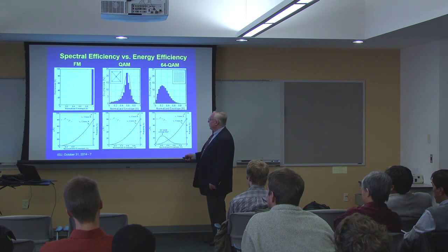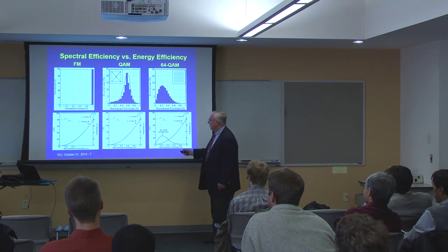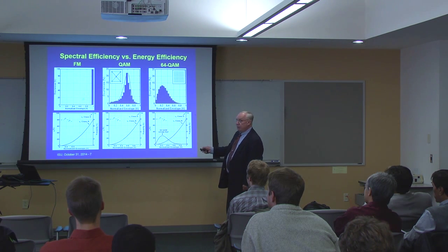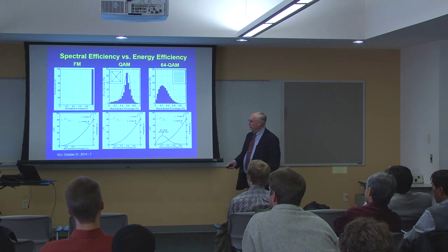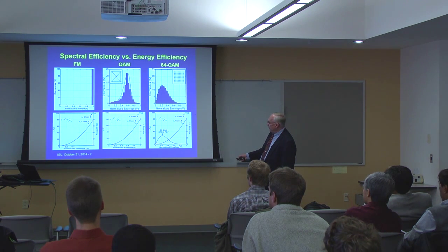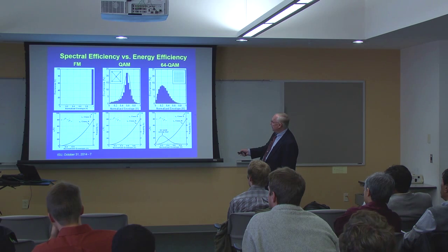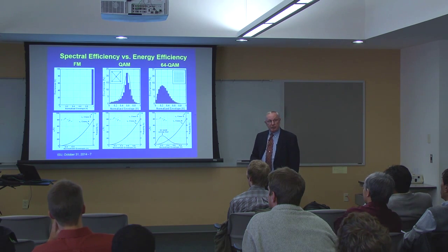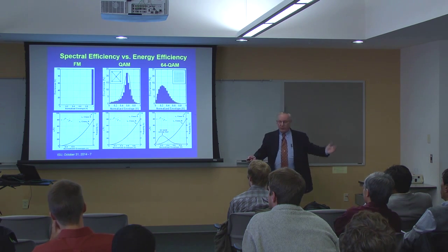So let's look at the corresponding efficiency curves. Well, if you only have one amplitude, you can use one of the switching topologies like Class E and get this ideally 100% efficiency. Great. If you have something where the amplitude varies like this, you might consider using a Class B stage, for example, and the efficiency looks something like that. What's the problem with this? Well, the peak efficiency, as I said, is great, 78.5%.